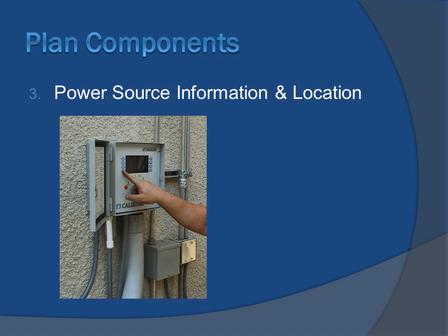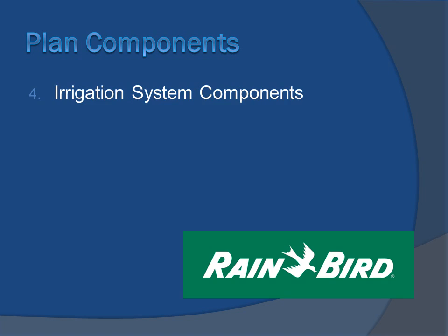All right, but your power source, where are we going to locate the irrigation controller? Inside the garage, inside the house, outside? I like them outside. I like exterior weather clocks because I don't have to depend on the client to be home to let me in. If it's on the outside and you get an exterior weather box, you can go and run all the systems without the homeowner being there. Pretty smart. Why do so many people want to hide that in their garage?